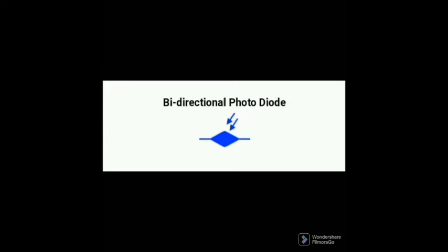A photodiode converts light energy into electrical energy. When light hits the p-n junction, it creates an electron-hole pair which flows out as electrical current. This symbol represents a photodiode. A generic photodiode is designed to operate only in reverse bias. This type of photodiode operates in both directions. This type of photodiode is made from two diodes in a single package with one common terminal, i.e.